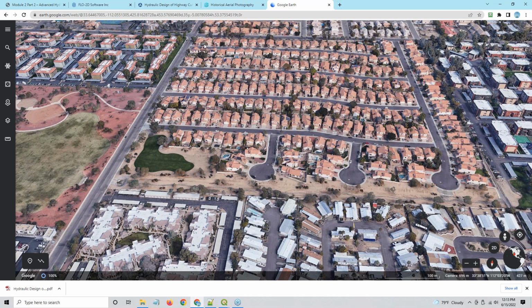And so this development community cannot increase the water depth on its downstream neighbors. And it can't just rely on this basin only, because this basin was designed for the street flow, not the water flow, right? So if you have a development community, or you're doing a design model, you can't increase the depth or the downstream water surface elevation on your neighbors.